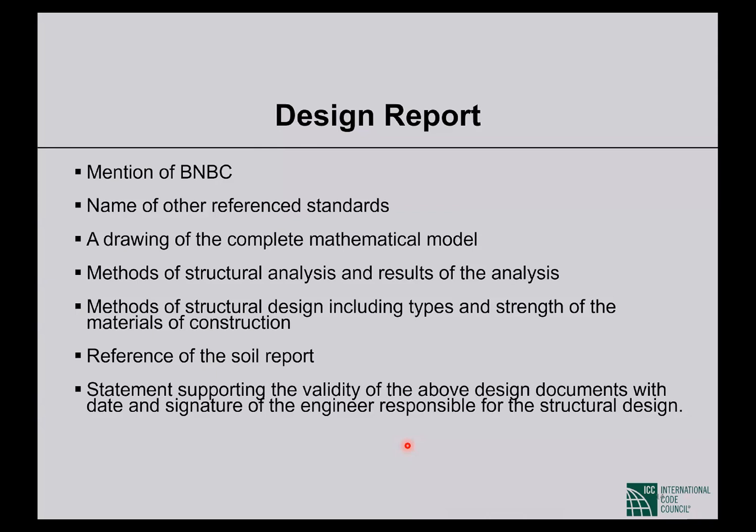Let me give an example. In order to understand the effect of the soft story building, we need to model the brick infill walls. So how can we model? We can model it in many different ways. For example, we can model it as struts.